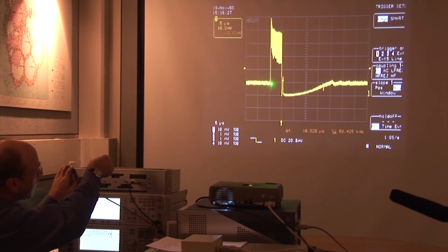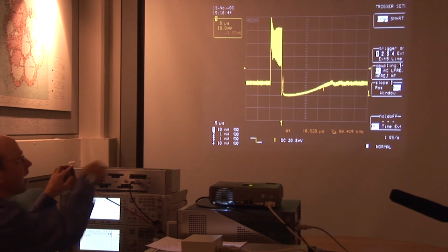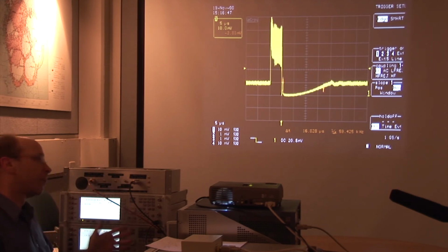The low noise amplifier response right in here is actually dropping down like that. We just can't see it because it's being masked by the pulse activity. And then when the interference pulse turns off right here, we see the recovery of the amplifier coming back up to full performance. Again, if you see that happen, you're overloading the low noise amplifier.